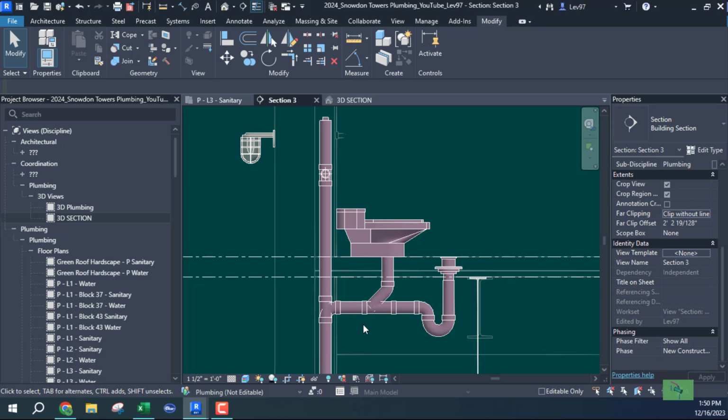But it can be frustrating, and it can set you back if you dwell on the fact that you need to have Revit count up plumbing fixture units, whether it's the water supply fixture units or the drainage fixture units. Those two are what you would want to keep track of. And to ask Revit to do that in a full-scale project can be very challenging.